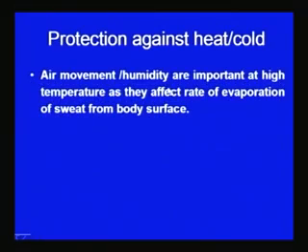Air movement and humidity are important factors that affect heat transfer, especially at high temperature. They are important at a high temperature because they affect the evaporation of the sweat from the body surface. The higher the air movement, the greater the evaporation, and therefore the body will be able to lose heat